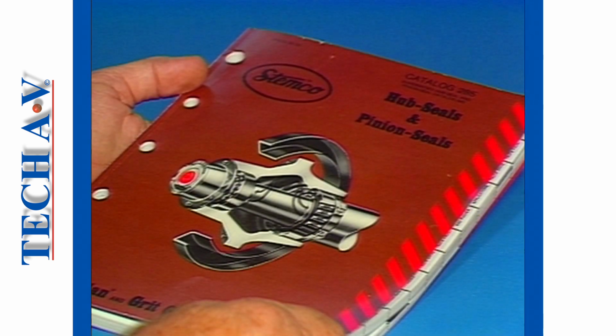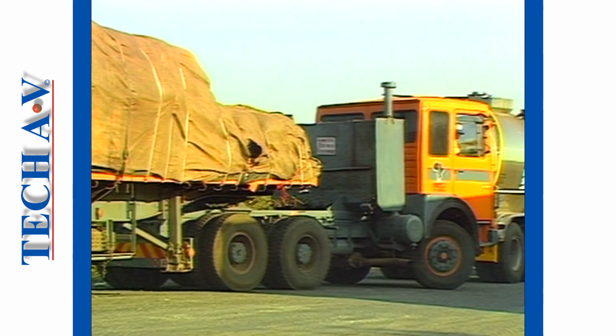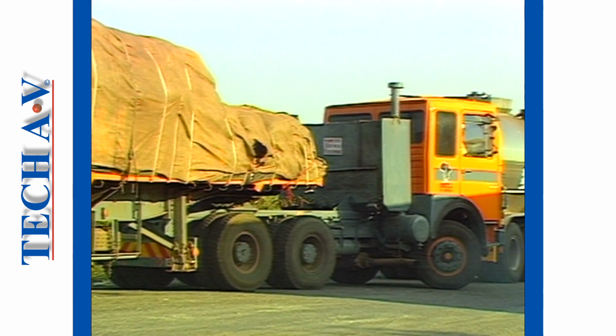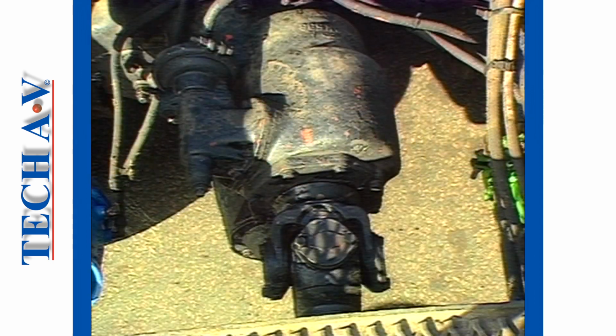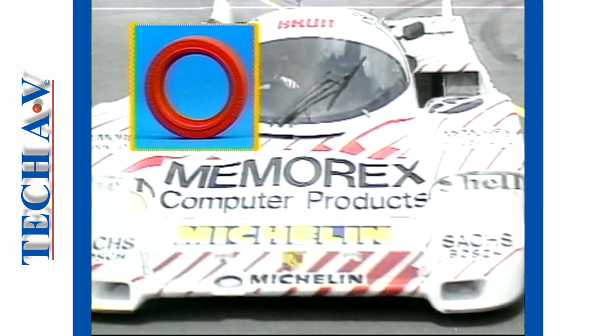More suited to higher temperatures, up to 160 degrees, are polyacrylic seals. Such seals can also cope with extreme pressure lubricants, as used in some vehicle differentials. Next are the silicone seals, popularly used for automotive engines, where high speeds and high temperatures are encountered.